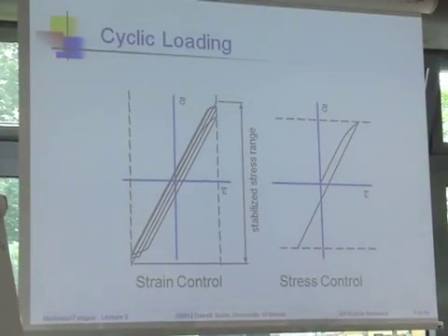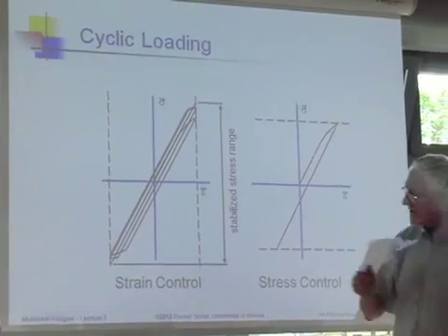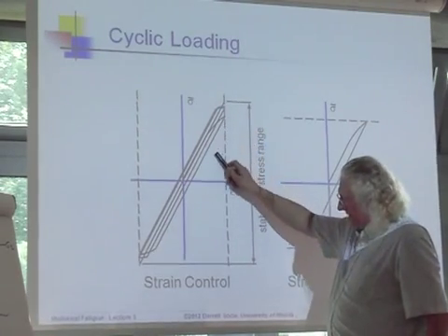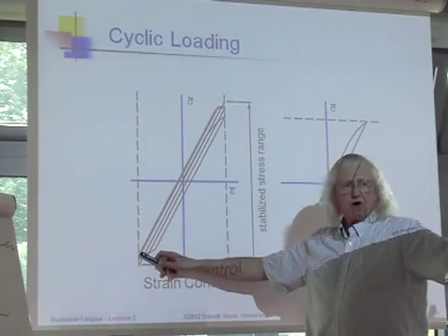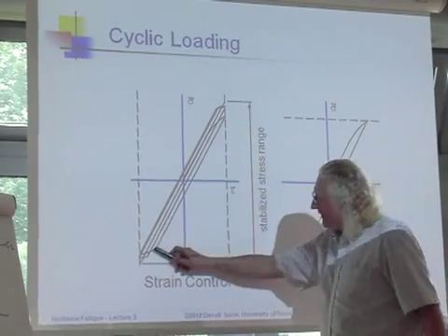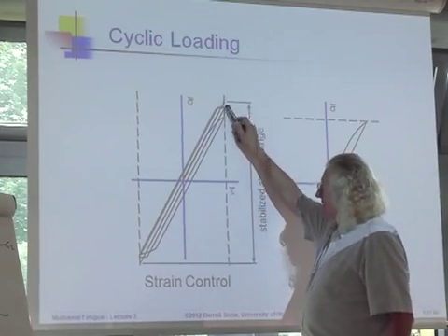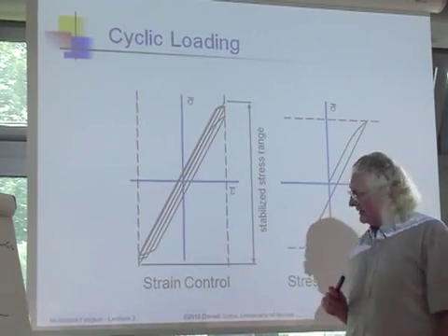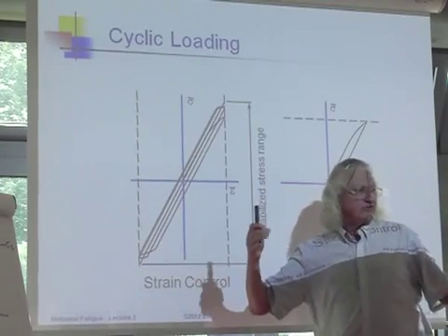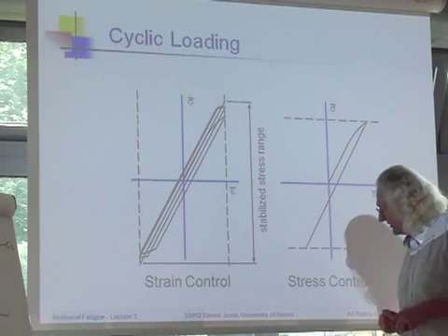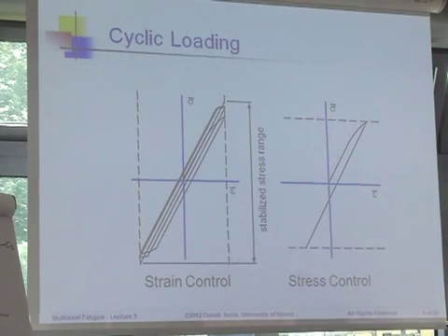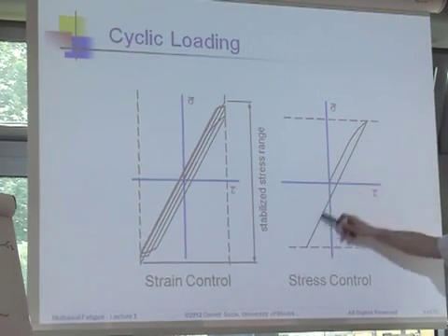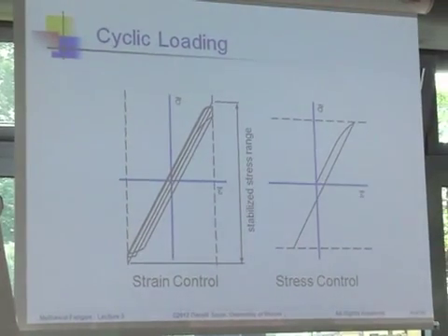And this is why, in fatigue, if you work an isotropic hardening model, maybe when I load something on the first cycle, I'll get some plasticity, but it becomes stronger. And then when I load this in compression, it will get a little bit stronger yet, and finally I might reach a scenario where it is all elastic. This was the basis of the Dang Van criteria that I mentioned. Doesn't have to be all elastic. Well, I could reach the saturation stress and then get plastic deformation. If you test in a constant stress limit rather than a constant strain limit, then it loads up to some stress and you unload to that stress and then it's always elastic. That's an unrealistic scenario, but that's what would happen.